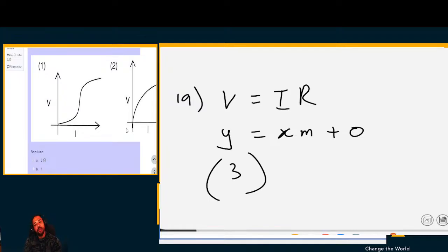It depends. You can choose in this case because you can measure either one. They adjusted the current and then they measured the voltage. They chose how much current to let into a system and then calculated the voltage, and it should give you a straight line. But if voltage was the dependent variable, that means the gradient would be one over R, right? Yes, the gradient would just be the inverse of the resistance.